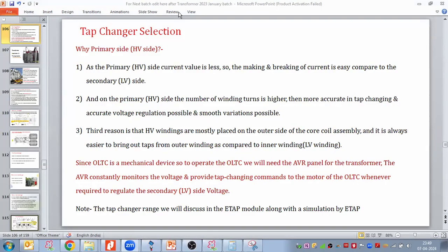Raghav sir, one doubt. Yeah, Raman. Regarding the transformer installation, you have said that the direction of withdrawal needs to be mentioned by the vendor. How will we normally decide which direction we need to withdraw the transformer? That may be towards the HV side or LV side. How will they decide? You can ask him to mark it, because there is a wheel attached at the bottom of the transformer.